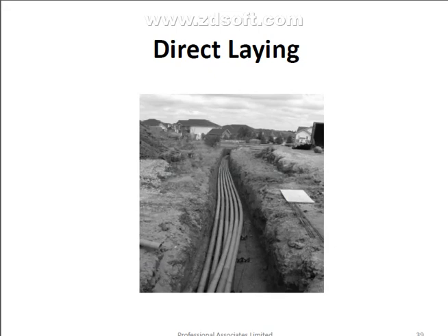If we are talking about the diagram, in direct laying it should be 1.5 meter deep, depending upon what type of cable we are utilizing.